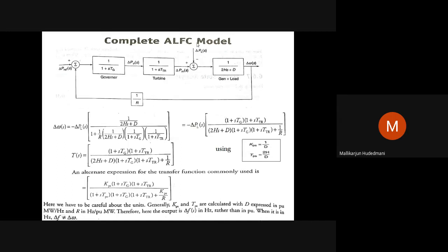Therefore, delta PL refers to a minor change in frequency insensitive load, and D refers to the frequency sensitive loads of the locality. Together, this right hand side block refers to the generator and load together, and its demand is the electrical demand and the area's reflection by D. This gets an input from the mechanical part and the load on that. This difference plays on the generating area and is transformed into a variation in frequency.